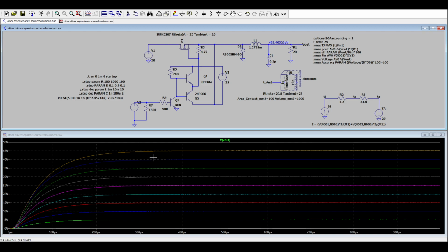If the converter is run for 5 minutes, 300 microseconds of time is going to be negligible. But as we can see here via the SPICE error log, the efficiency is roughly from about 60 to 95%, with the highest efficiency at the highest duty cycles. If I were to decrease the time it was running, it would increase dramatically, as demonstrated in my report.